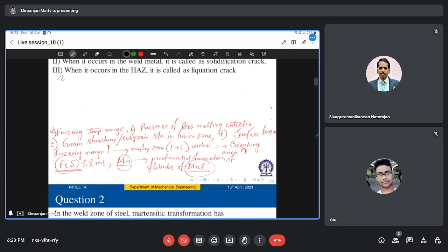So as I was saying, coarse columnar grains are more susceptible to cracking compared to fine equiaxed grains, right? Now, first, fine equiaxed grains can better deform to accommodate these contraction stresses, or relieve stresses across these interdendritic boundaries. And secondly, liquid can be more effectively fed to these incipient cracks to promote healing in fine grained materials, where these grain boundaries run in all directions, right?